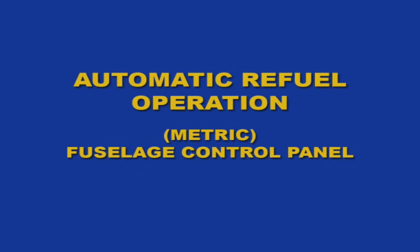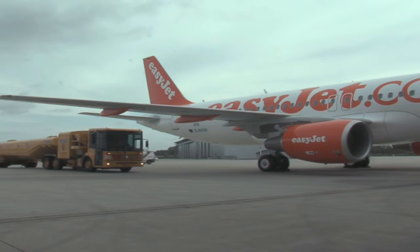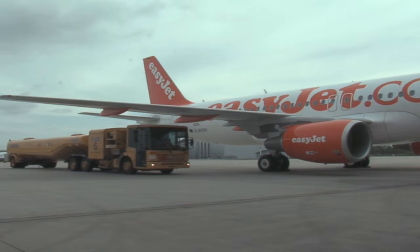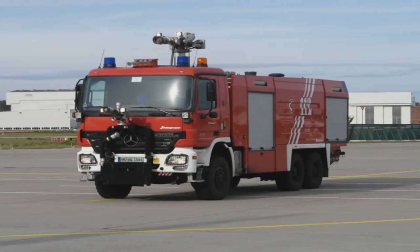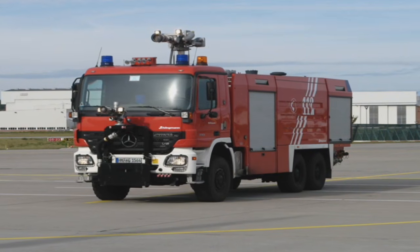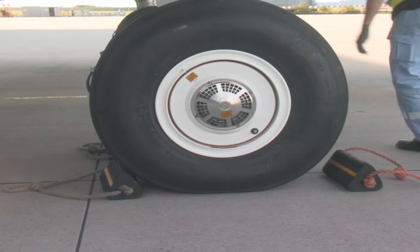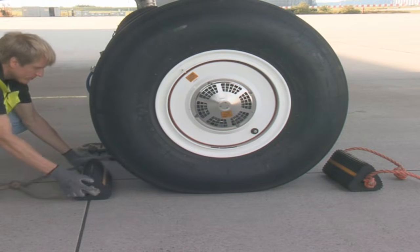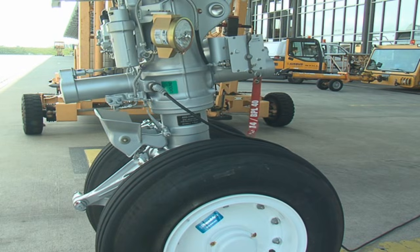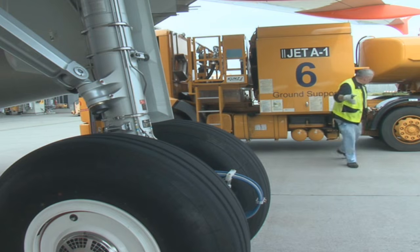Automatic refuel operation. Put the flaps and slats into the 0 position. Firefighting equipment must be located near the aircraft. Make sure that the chocks do not touch the tires. Make sure that the aircraft and the fuel tanker are grounded correctly.